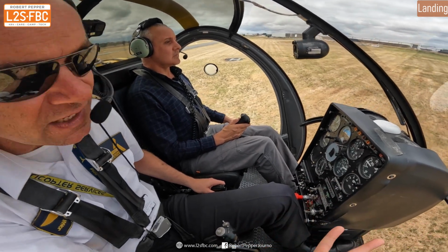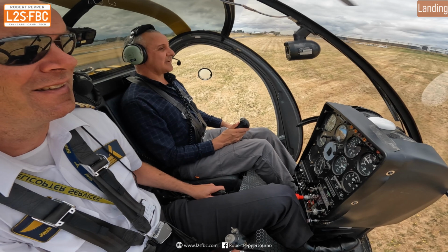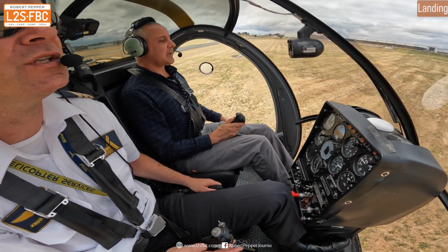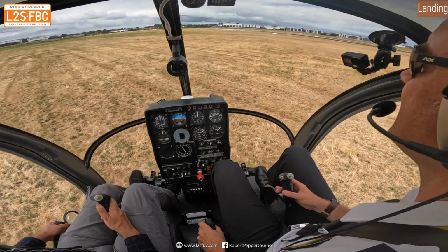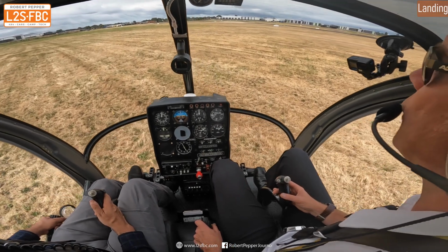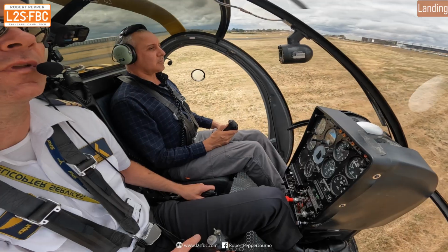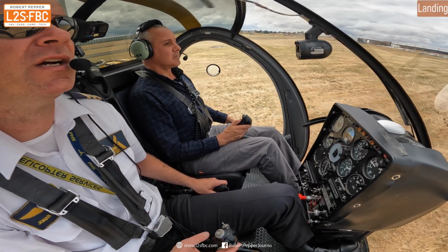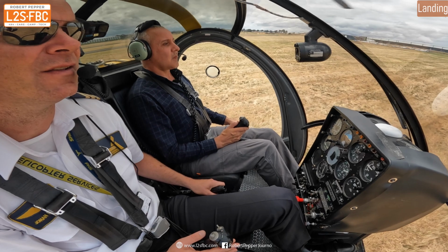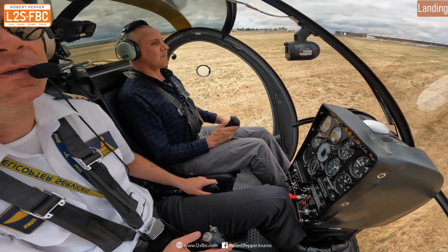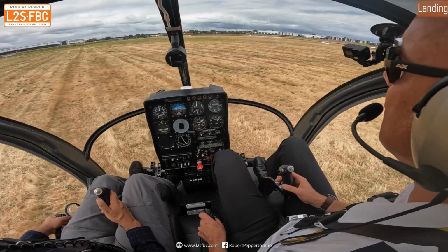Now I then need to establish a hover and then just slowly bring that collective down. I'm looking well ahead here. I'm really conscious of not over controlling, because the closer you are to the ground, the more the ground seems to move. 1,000 feet up, it doesn't seem that much. And I'm just looking ahead now, and you can see with this that was a mistake, but just bring it back. Don't want to over control here, don't want to get excited. I'm still keeping it pointed pretty much into wind, just down and down and down, and out of the corner of my eyes now I can sort of see the grass move. I know we're getting closer, but I'm just still looking ahead and just thinking, okay, when's the ground going to come up?